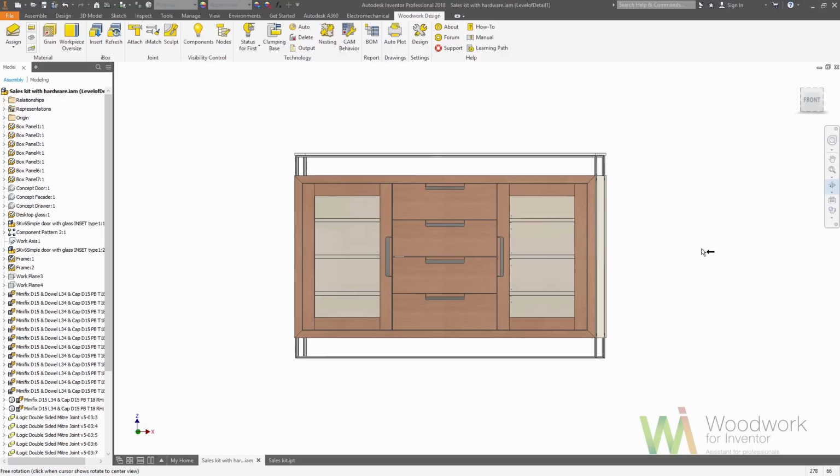We set the materials, we added the hardware, generated the holes, made the specification by setting the real materials and codes. Then we went through the drawing generation, the CNC program generation and the nesting. And finally, if you found that something is wrong, maybe I don't like the size of the final model, I can just go back to the very initial step and set the new parameters in order to see what will happen then.